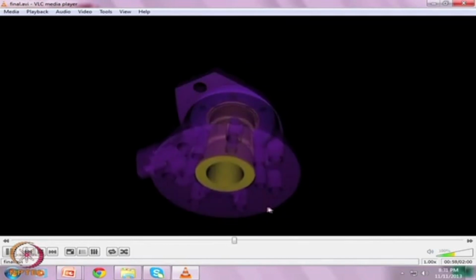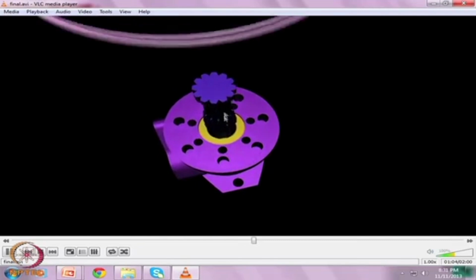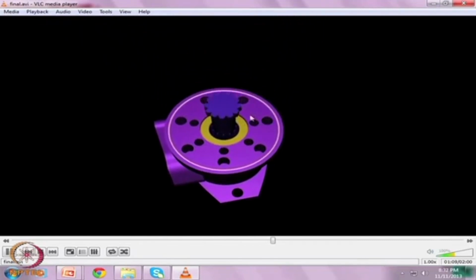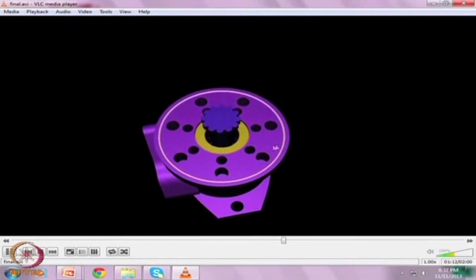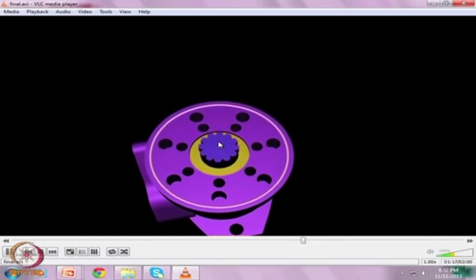Now, look at this. This cardan shaft will go inside. Now, to maintain this, how these grooves and then the interchamber are linked: actually, in the cardan shaft, all the teeth on both sides are in the same phase, there is no lead or lag, and in the star the splines or the gears are made with a particular sequence.